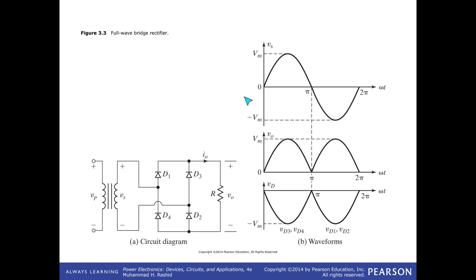Then this is the voltage transferred to the load, and for the second half of the sinusoidal waveform, the negatively positioned diodes receive a positive anode-cathode voltage, therefore they inherently conduct, D3 and D4, transferring the inverse voltage. Inverse voltage means the inverse of this one, and this is the output. That's the output for a resistive load, by the way. There is no energy storing device in your secondary.